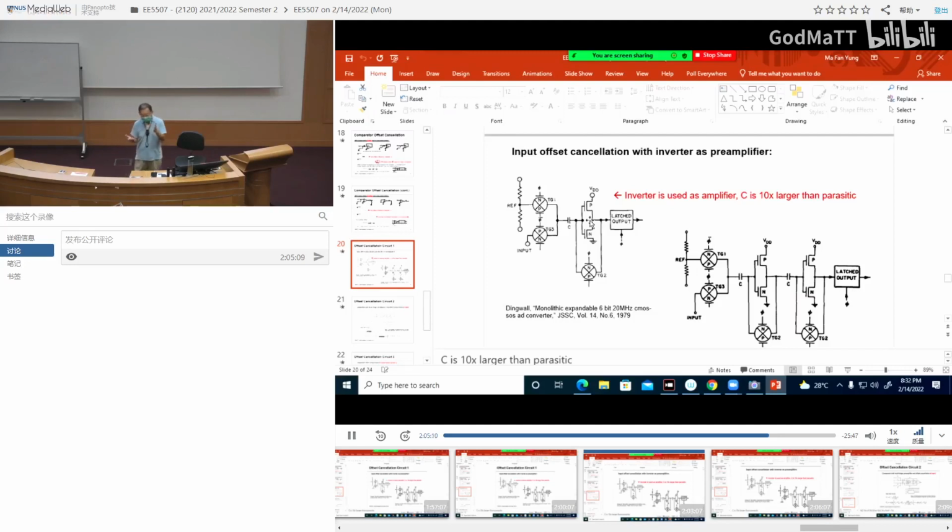Why do you say that? Because we found that when you measure at high frequency, the capacitor actually has some inductance. The inductor actually has some resistance. So at high frequency especially, you see the effect very clearly. The ideal capacitor curve in the frequency domain is coming down, it's 1 over S. But because there's resistance, the curve actually will change shape.